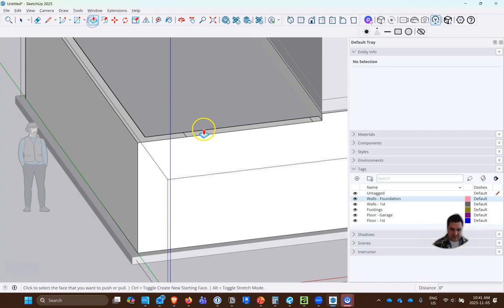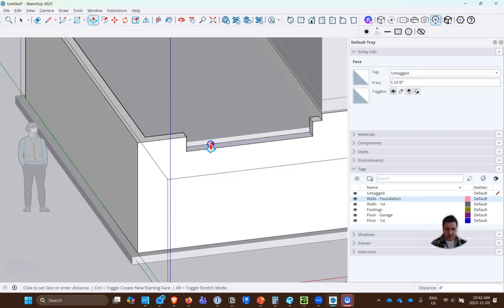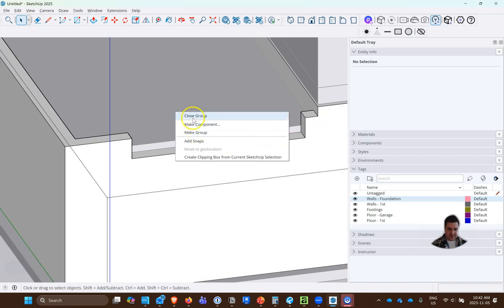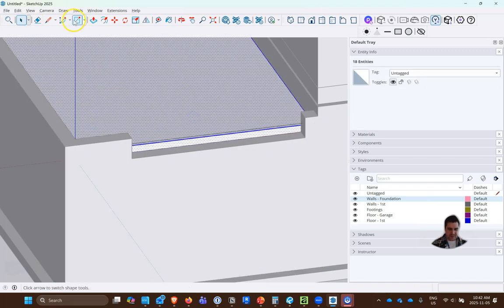And so now that we have this, we can extrude this down to our floor height. The reality is when you pour a floor in a garage, typically you would actually lower the opening lower than the floor, and then you'd have the floor spill out, so you don't have that gap like we see in this model right now. But I think for modeling purposes, that makes sense. If it makes you feel better, you could lower it down like this, and then we would just have to edit the slab and make the slab go out.